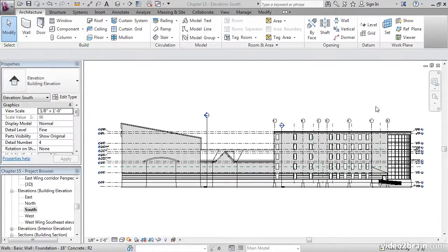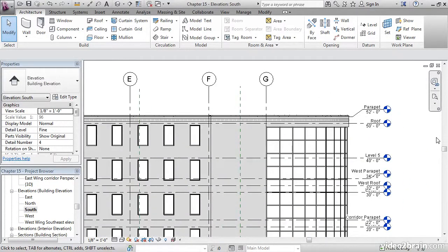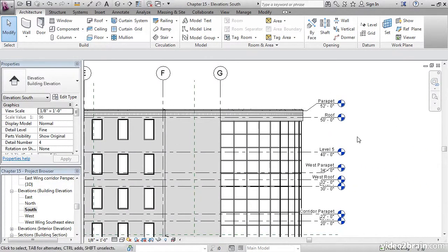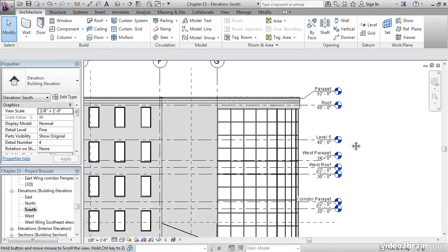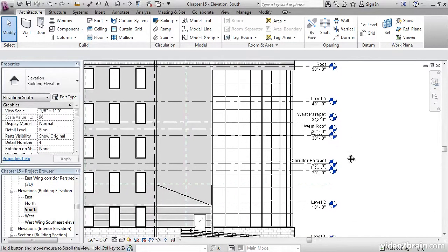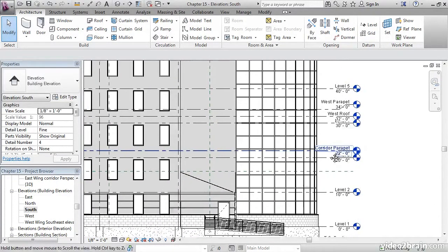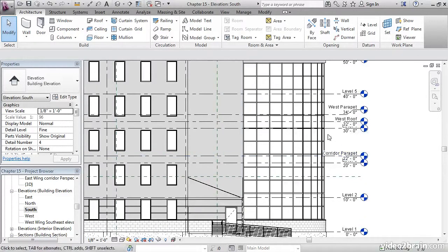In this lesson, we'll learn how to constrain our walls to specific levels. Since we have levels, it's time to talk about using them. Levels drive Revit. They also control how our walls begin and end. Every object in Revit knows which level they're hosted by. Walls take it a step further.